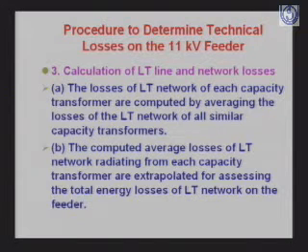But I would recommend that, to the best possible extent, it should be avoided. Because the method says that we work out the losses of the LT network of each capacity transformer, and then we average out for each LT network, and then we compute the average losses of the LT network radiating from each capacity transformer and extrapolate it. Basically some sort of assessment.